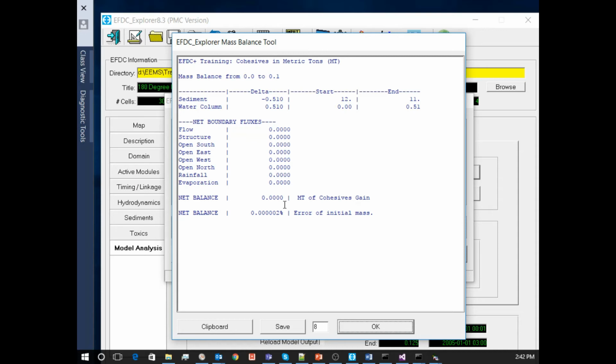It's very, very common for these flows not to balance out. So you usually have to post-process and either add makeup water, because of groundwater, or say that your flow measurements are incorrect. But if your volume elevation relationship is good and your inflows and outflows are measured and you want to use them straight up, you're going to have to do something else. The makeup water, and then where you add it back, to your inflows, or?